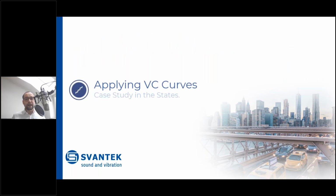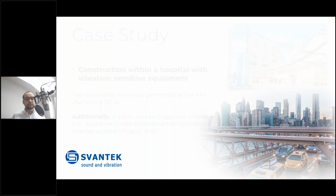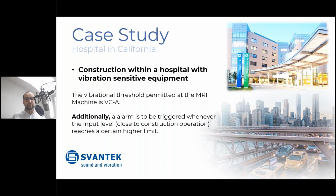So let's talk a little bit about applying VC curves. A very interesting scenario that we have is in a hospital in California, where construction is ongoing inside a hospital with an MRI machine. The MRI machine has been specified to have a level not higher than VC-A and is on a foundation that has been decoupled from the rest of the building, ensuring good insulation from vibration.